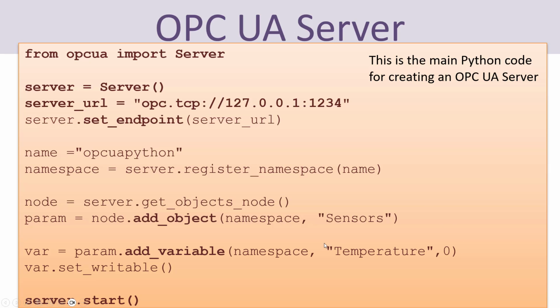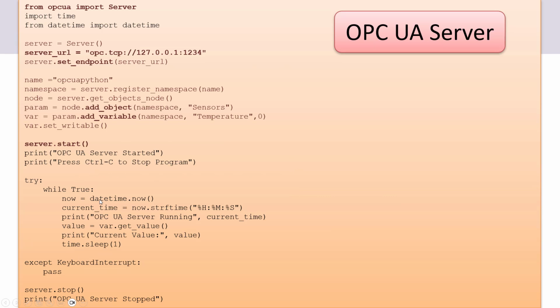and then we have our two OPC UA clients that should now connect to that server. You can also, of course, improve the server. You can create a while loop like we did for the OPC UA clients applications. So here I have done the same. I just put this code and added or improved it by using a while loop, and I used a try catch in order to stop the server when I click this Ctrl+C button. So basically now we have 3 applications, one OPC UA server written in Python and 2 client applications, one for write and one for read, also written in Python.